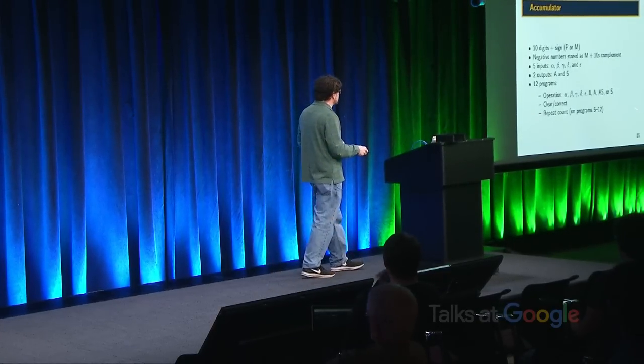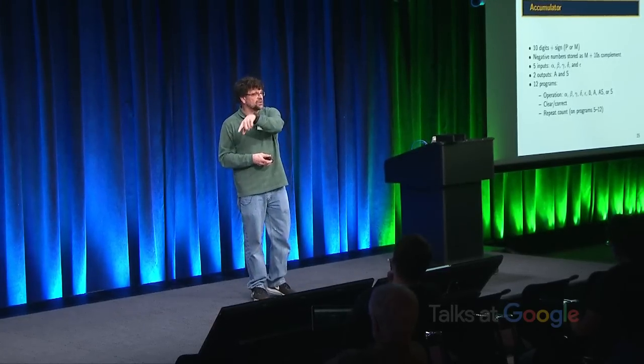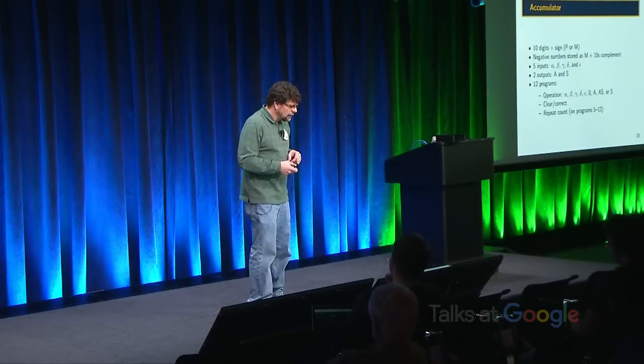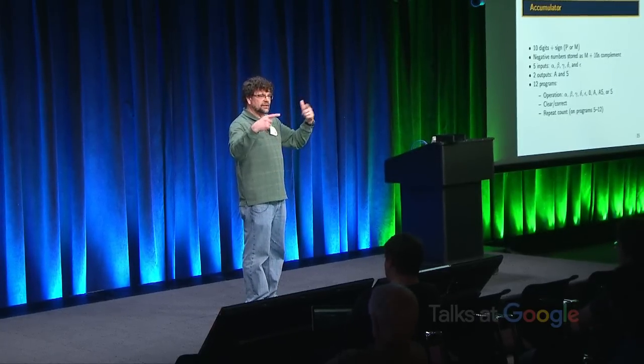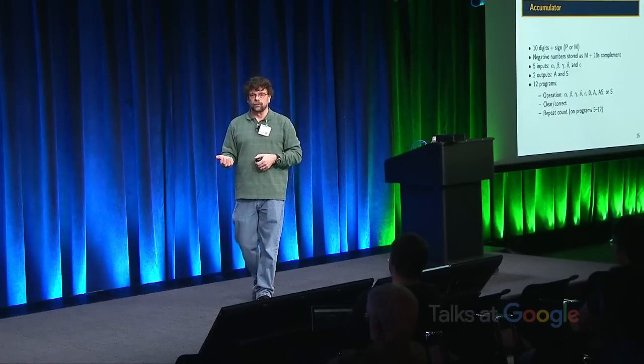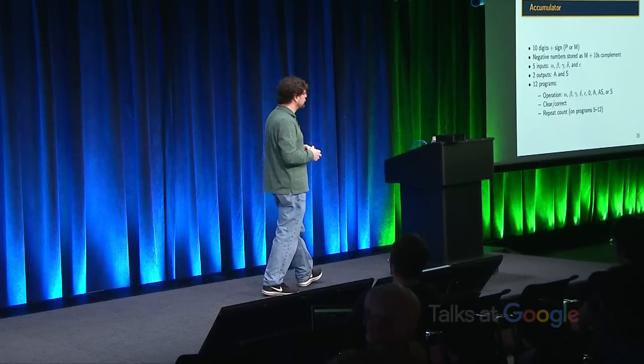The other thing we've got is a nice little repeat mechanism. So if I want to add 3x to y, then I don't have to set it up as 3 separate operations. I can set it up as one operation in which x is transmitted 3 times and y receives 3 times. So small integer coefficients in your equations don't actually have to go through the multiplier. You only need the multiplier when you're multiplying 2 variables together.